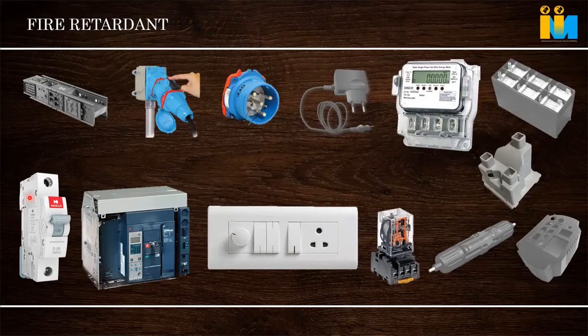Robots are there, so there will not be any loss or stoppage. It will be continuously running. The mold itself is made so robust, and inside the mold they put a lot of beryllium copper, not touching the part, below the part, and water line and oil line will be passing through that. So quick cycle time and a very, very thermally robust mold will be made for the application.